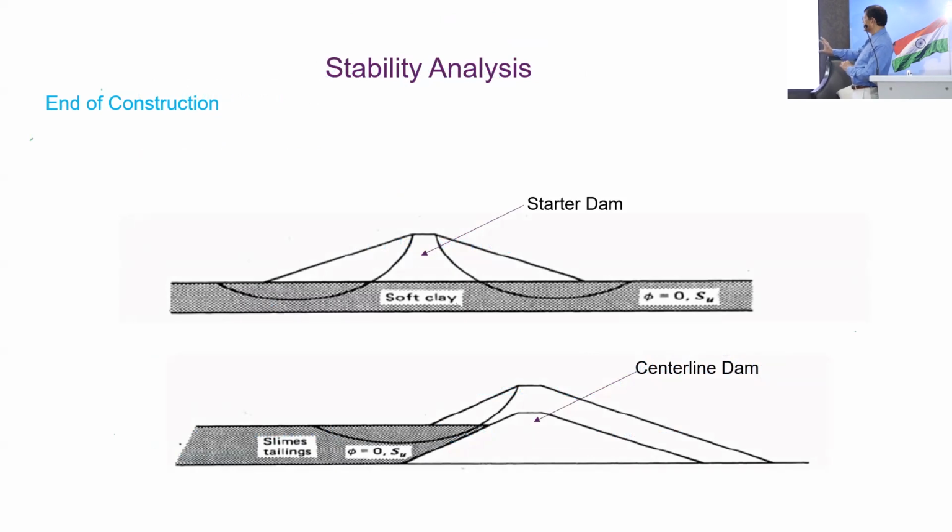Whether it is a centerline dam or an upstream dam, we also have a slide through the tailings, because in the upstream dam your foundation is the tailings, and in the starter dam you have a soft clay. If you have soft clay in your foundation, because most of the plain areas where we design these, you have a plant and near the plant you are designing the tailings dam. In those areas it's possible you have some soft clay there.